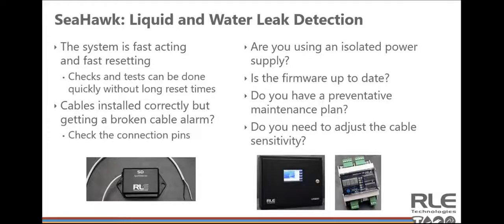As well, when working on mechanical systems, specifically chilled water systems, be careful of the bare pipe areas, ball valves, pressure reliefs, other things that don't have insulation on them. If you're running a 40-degree Fahrenheit comfort cooling system and you've got the standard temperatures there, you're going to run into condensation points. Just be cognizant of that.